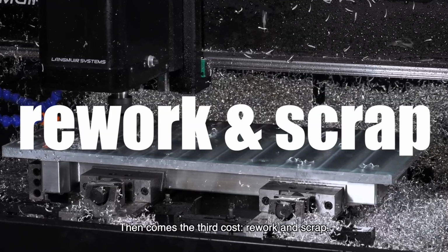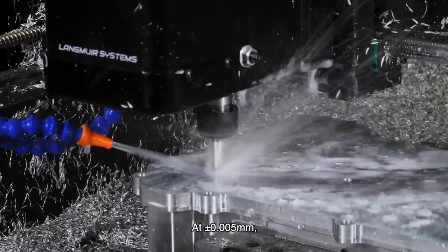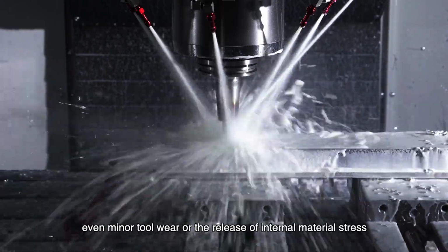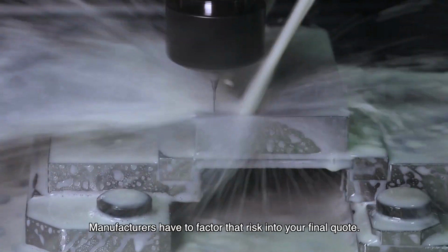Then comes the third cost, rework and scrap. At plus or minus 0.005 millimeters, even minor tool wear, or the release of internal material stress, can reduce the yield. Manufacturers have to factor that risk into your final quote.